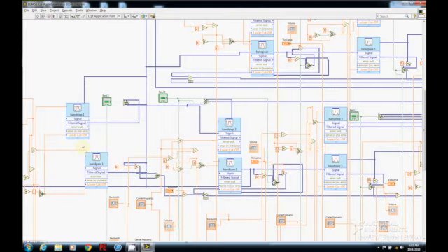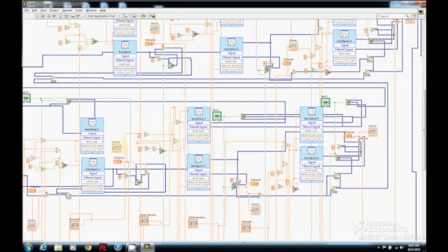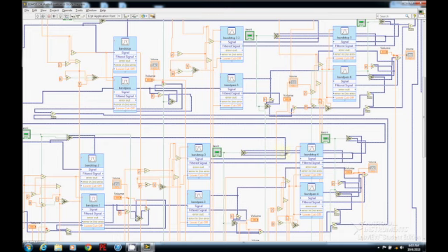The equalizer design consists of 7 bands made up of a set of bandpass and bandstop filters. Bandstop filters are implemented in a series manner to isolate the specific band from the original signal. Concurrently, in the parallel implementation, there is also a set of bandpass filters corresponding to their respective bandstop filters. These allow us to customize the center frequency, bandwidth and gain of the different bands.